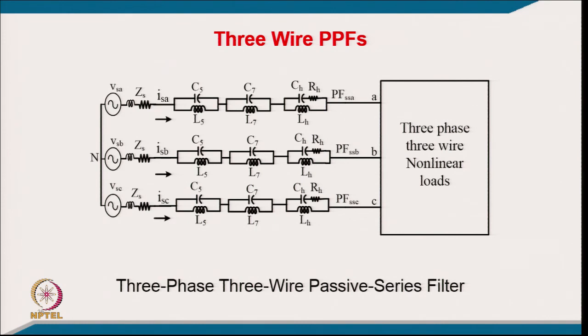And if you go to the 3 wire, 3 phase non-linear load, which are very large in number, you have a 3 phase direct rectifier with capacitive filter, then adjustable speed drives, used in a large number of applications like wastewater treatment plants. We were discussing where you have unidirectional power: pumps, compressors, plenty of applications are there. We use air conditioning, where you are taking only unidirectional power flow. You prefer to use a simple diode rectifier, and after that you have a 3 phase inverter feeding an induction motor drive. There of course, we use 5th harmonic block, 7th harmonic block, and then 11th, and all higher harmonics you block with this also.